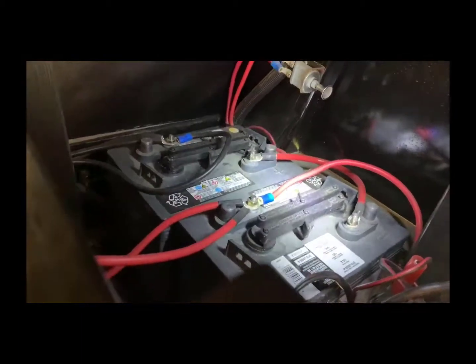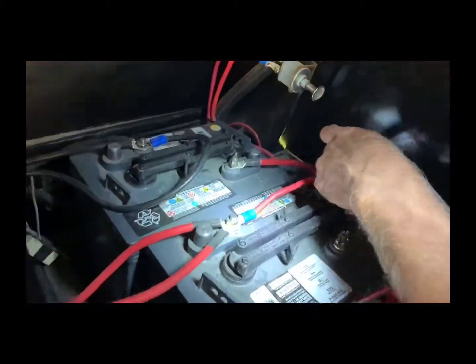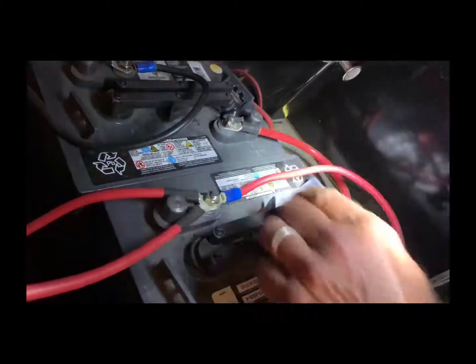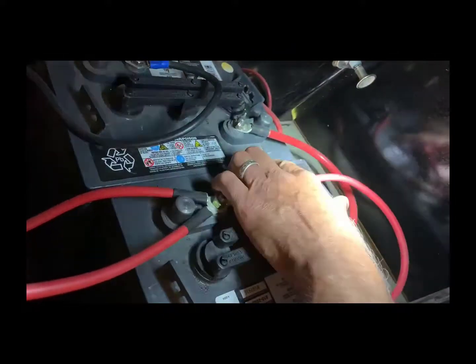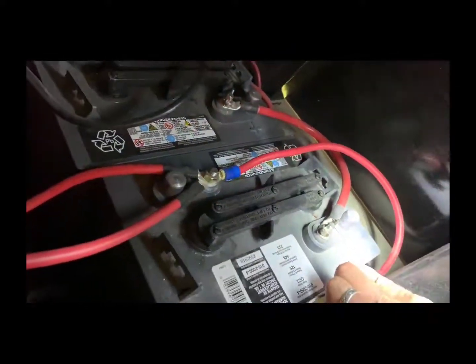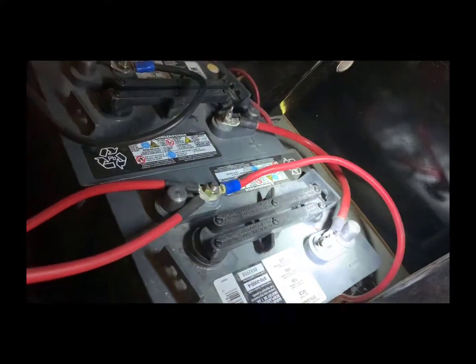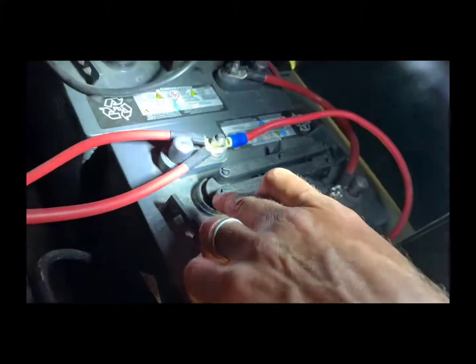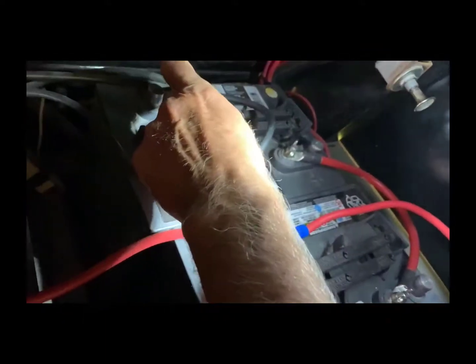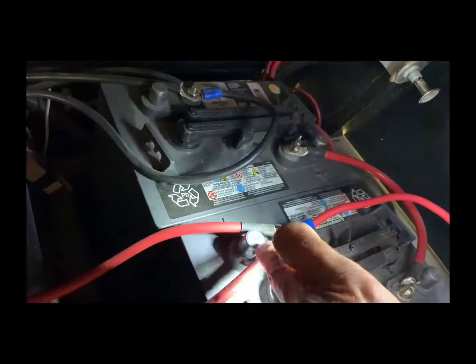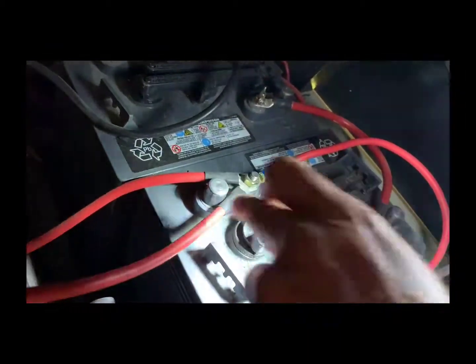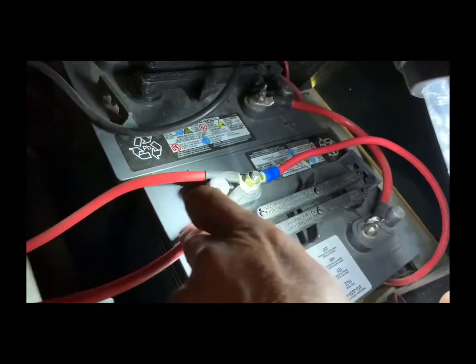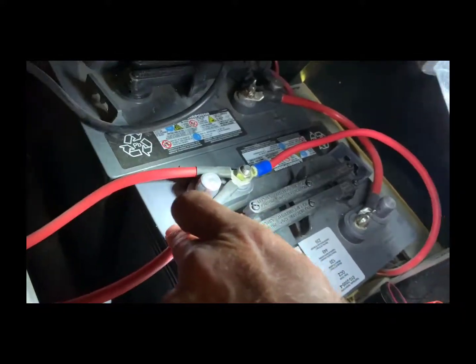If you look closer, look at this wire here that's connecting the two batteries together. Notice how it's going from the positive terminal to the negative terminal to give you that series connection. And the 12-volt connections are across the two series connected batteries here. Okay, so over here you can see the negative for the system and the positive for the system. There's a few wires that run a few different systems here, but they're all 12-volt systems.